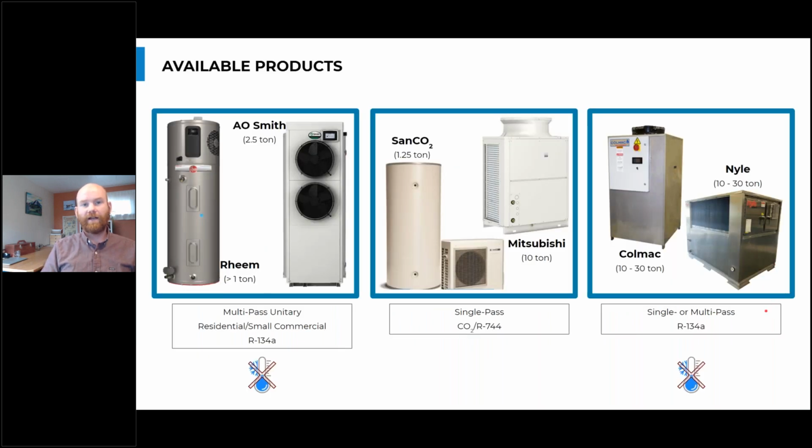And we have a handful of available products today. We looked at some of the residential products that were introduced that are using the unitary or integrated style heat pump water heaters. And a reminder that that's the heat pump water heater packaged with the storage tank. And typically that heat pump water heater sits on top. These are most commonly sized for residential loads. But recently, A.O. Smith has released an integrated or unitary heat pump water heater that has a larger storage tank behind this heat pump unit there on the front face.